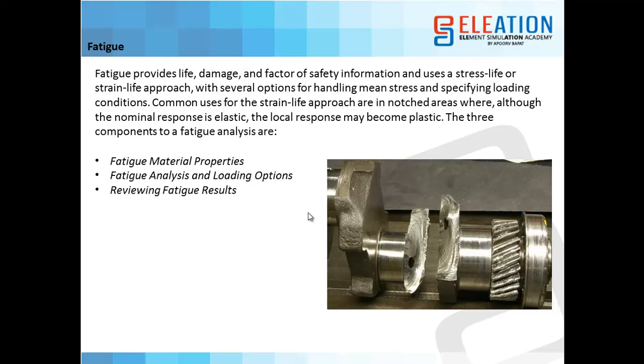So that helps me decide whether I have designed that component as per my requirement or not, because sometimes we see that components are designed in a very abrupt way, and they are over designed, and they can work a longer time, and we don't actually want those components to work for a longer duration. So we are mainly targeting such events where my component will work for some duration, and we require a component to work for a certain duration. So we can calculate the fatigue life, and with the help of fatigue life, we can reduce the weight or change the material, and reduce the life or make the life as per my requirements.